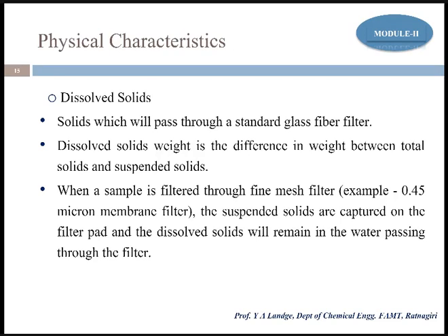The particles are accumulated or captured on the screen, and the dissolved solid remains in the water passing through the filter. So if we have a membrane filter, the suspended solid can be easily captured on the membrane, and the dissolved solid passes through it, because the size of the dissolved solid is less than 0.45 micron.